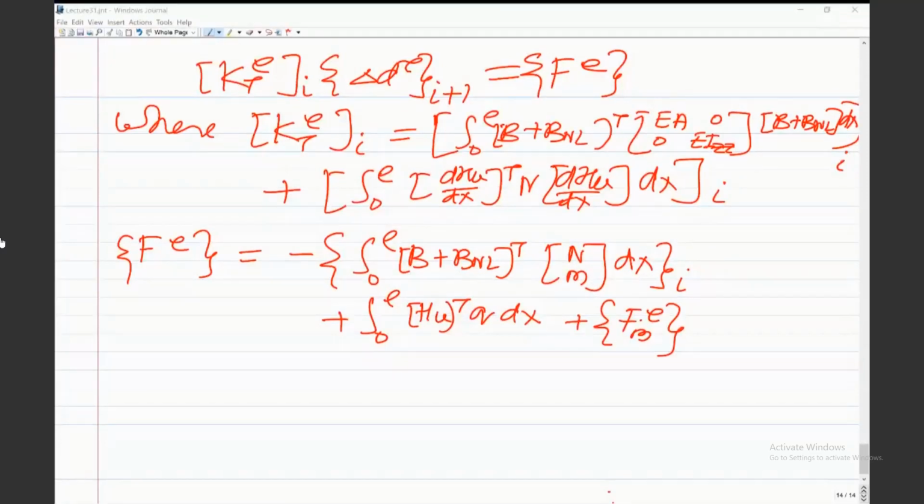Then you need to consider it, because when both the ends are fixed and you apply a transverse load, when the beam deforms, its curved length is going to be more than its initial length. So the length of the neutral axis in the undeformed configuration would be different from the length of the neutral axis in the deformed configuration. So you still need to consider U naught.